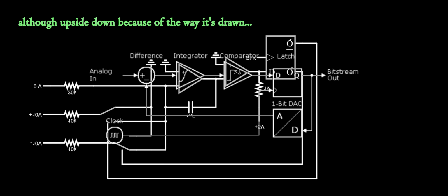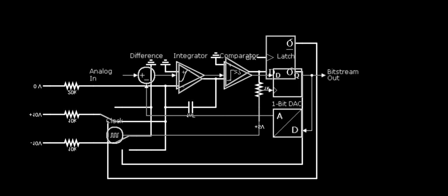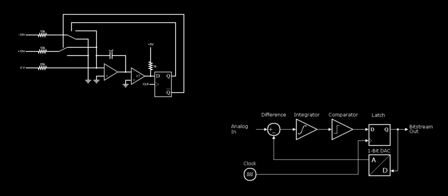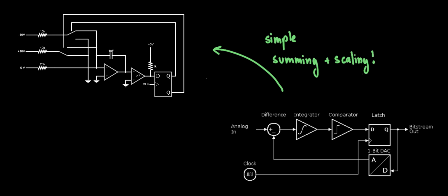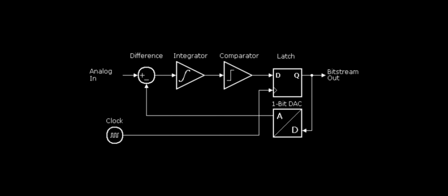The modulator's block diagram can be superimposed almost perfectly on top of the simple multislope circuit. This is almost a divine miracle. From the delta sigma point of view, the multislope ADC is simply a first-order modulator without a complicated digital filter. And from the point of view of a multislope ADC, delta sigma is multislope but with added digital signal processing. A simple delta sigma ADC is considered integrating in that it uses an integrator to accumulate the error, that is, the difference between the input voltage and the feedback voltage,